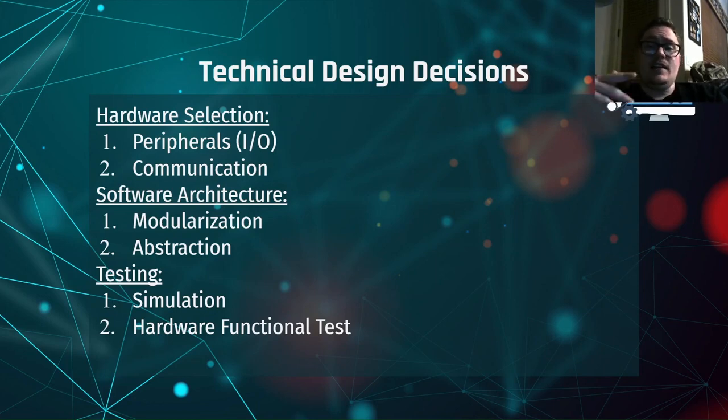But aside from that, I needed a way for the C program to communicate with the FPGA, and that was intuitively going to be the GPIO pins. That's probably the easiest way to do it, and so I elected to use those. And the LEDs were kind of the last-ditch thing, because I needed some extra output peripheral, and it was simple enough to add an LED to serve as the carry out or borrow out, showing that our operation produced a number greater than 16 or less than, well, not less than, but it will show that something came out that the number displayed does not contain.